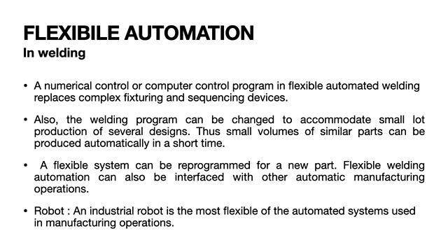A numerically controlled or computer controlled program in flexible automatic welding replaces the complex fixturing and sequencing devices. So that's what I was telling. These jigs and fixtures, which I have discussed before, are a very costly affair. This can be replaced with numerical and computer control programs, so that only the very minimum requirements of ensuring the position of the workpiece are actually needed.